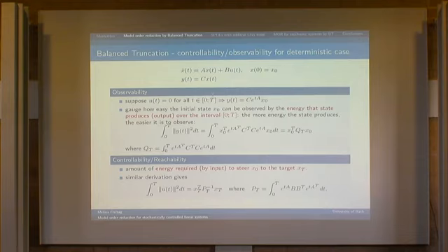Yeah. You're referring to a technique where, if there wasn't this output equation and you have just a state equation, you could look at the eigenvalues of A and cut off anything where the eigenvalues have small absolute value, and then do just a projection of the state equation without being concerned about the output. The thing here is I have an input and an output, and I'm really only interested in the output, which could be a complicated function, but it's just a linear function.